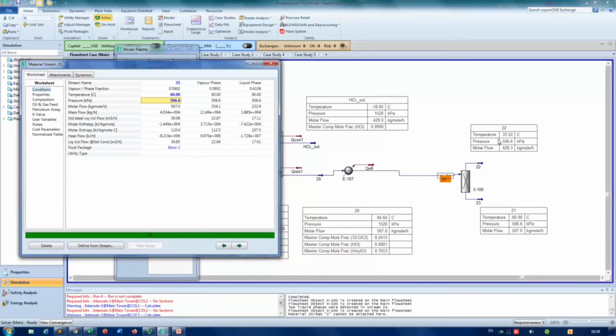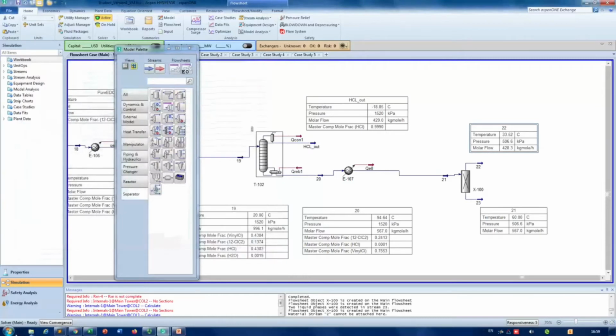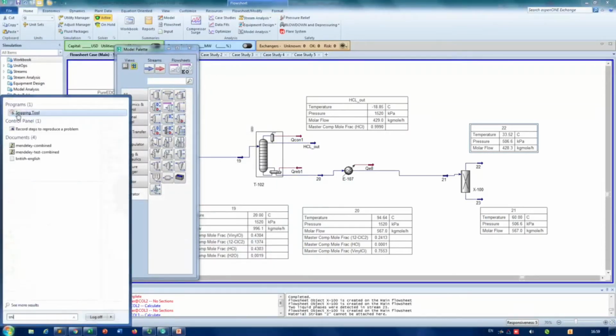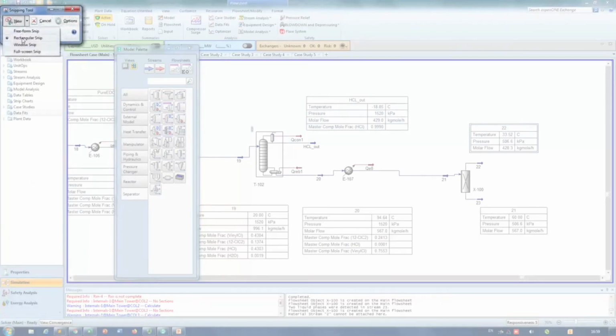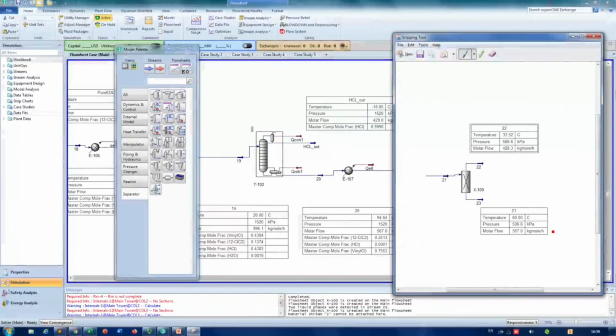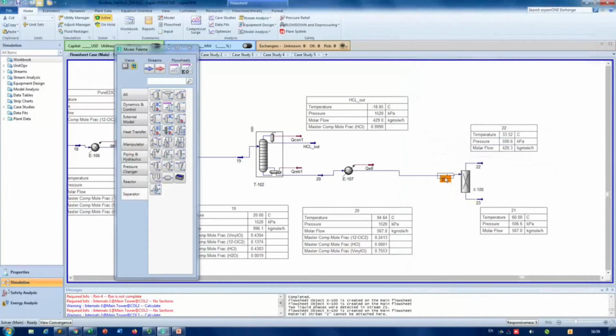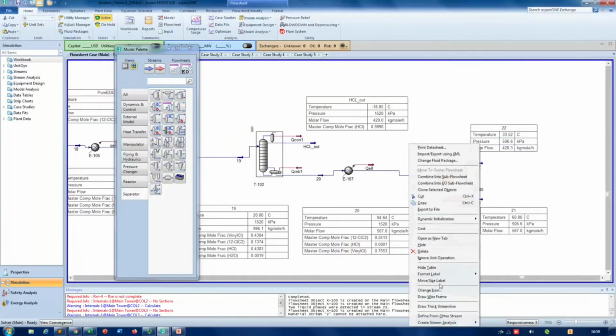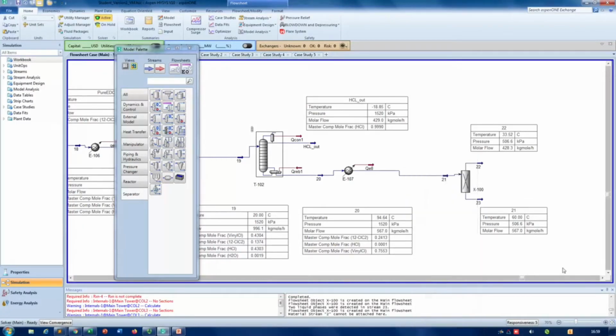So this means we can use normal river water to condense the stream that comes in the top. And in the bottom, the reboiler temperature is only around 60 degrees centigrade. A medium pressure steam is more than enough to create such a temperature. So I'm happy with this condition. Let's close this. Let's take a snapshot of all these conditions. Now we also have to close this. Let's also add a table for stream 11, stream 21. Sorry, what is this show table thing?